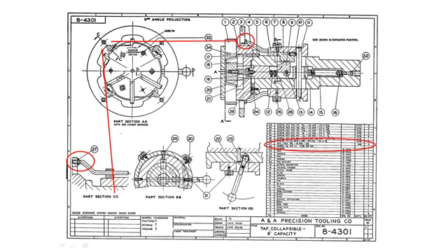And if you look down here onto our parts list, you can see that there are 4 nuts. Now, we have another one which you can see here. From all this information, we can just label one, and then using these other views and the symmetry of the shape, we can show where the other 3 are. So this is an example of how we can use section views to show a part, and also how we don't have to show every single part of that, but as long as we show how to locate one of these nuts, and then the rest we know are symmetrical.